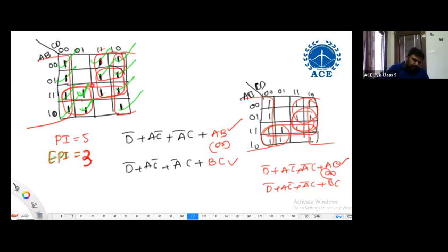But if you are observing this non-essential, in which we have this minterm, which is not covered by essential. So in this grouping also, first it must be non-essential to say it is redundant. We should go with non-essentials only. If it is covering minterms only covered by essential, then it is redundant. But no, it is not by essential. So here it is also not from essential. So two are non-redundant, but these two are selective prime implicants, if you are talking about redundant and selective.